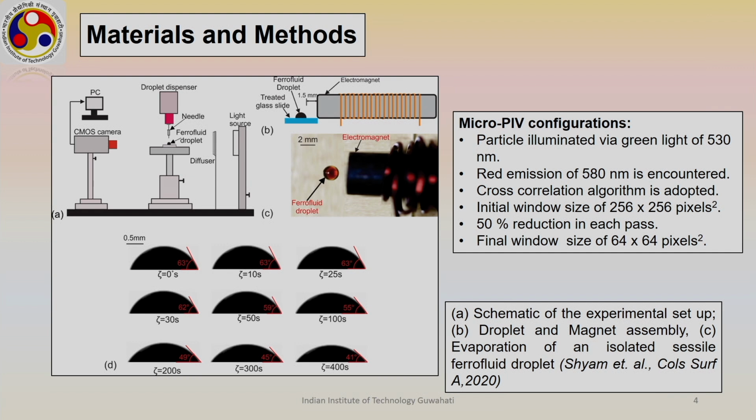So, if we do not mix iron particles, then what will happen? There will be internal flow structure because of the surface tension effect. So, there will be Marangoni convection and all other things, but to get sufficient insights in the flow field and to know the alteration of the flow field due to the nanoparticle which will be energized. So, nanoparticles will be energized by an electromagnet.